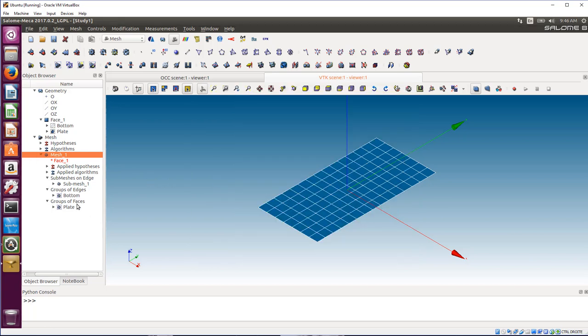Okay. Now, there's a common error here. If you forgot to create the mesh groups, you just export the mesh and then you read it in Aster-Study. You will find it strange that you're not getting the group of nodes to assign your boundary condition inside the Aster-Study module. So you will have to come back here and realize that you haven't created that.